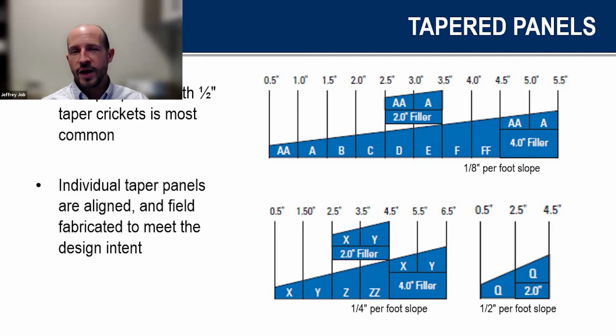So for example, if we had a fully mechanically fastened system, say our insulation package is an R value of 30, which is a pretty common number nationwide, those mechanical fasteners are acting as conduction points through that roof system. So they're essentially having the opposite effect of what the insulation is doing. They're conducting heat while the insulation is trying to resist heat. So with that said, a fastened system's on-paper performance is not going to be as good as what's actually happening on the job site, due to those physical connections. So you do lose some actual R value in a fully mechanically fastened system over a fully adhered system,